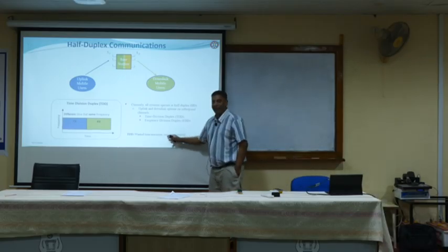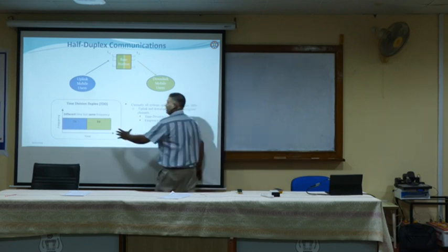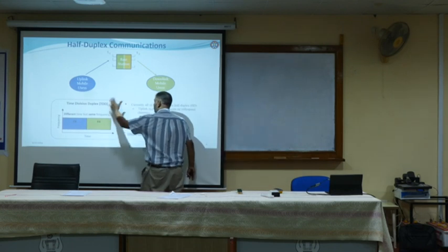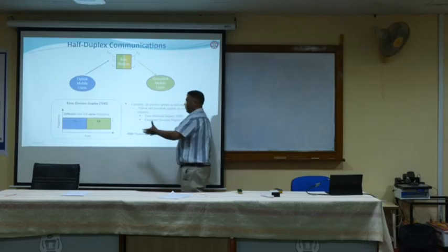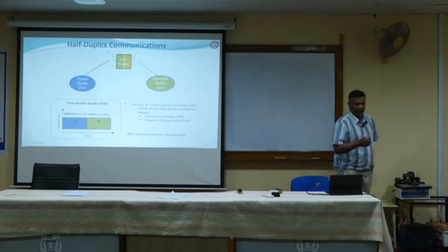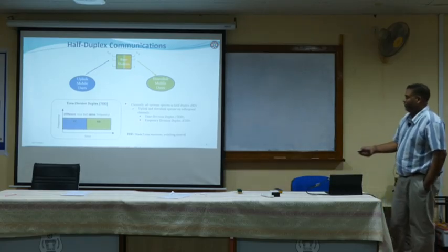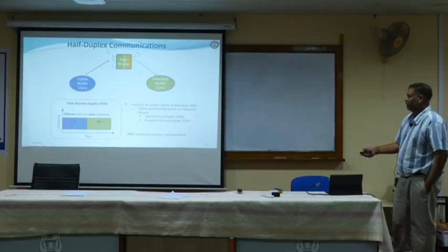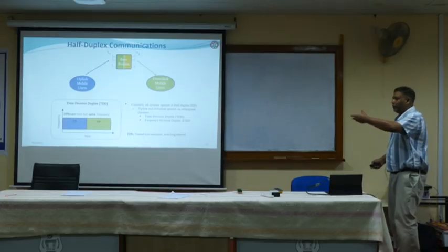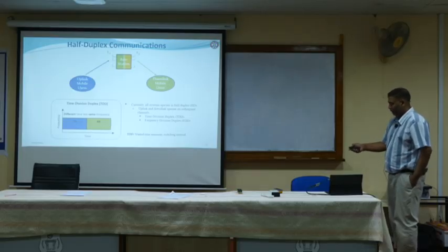You can immediately see the wasted time resources, because we want to use all the time for uplink, all the time for downlink, and all the frequency for both as well. If you do that, we can double the spectral efficiency compared to the TDD system. Another waste of time resources is the switching interval between uplink and downlink. So there's a wastage of resources as well.